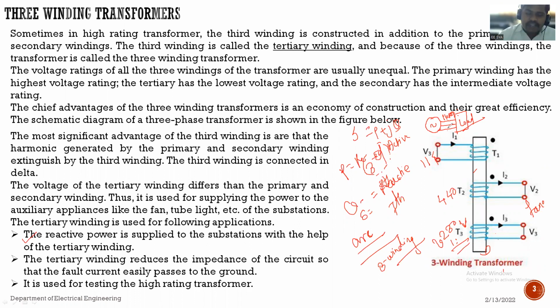Okay, this concept is in detail in your switchgear subject. See, the active power can be flowing from generator to load, and for the compensation, reactive power can be fed from load to generator. So the addition of that is nothing but the total power fed by generator, S equals P plus jQ. It is nothing but complex power. So complex power, we can call it the apparent power also.